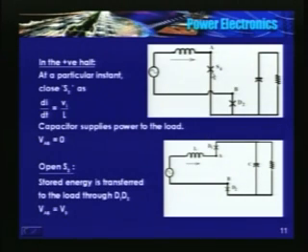After some time, again depending upon the control strategy, open S4. Don't need to do anything to S1. We know that inductor current should be continuous. It was flowing in this fashion, but then there is D1. So current will flow through D1.